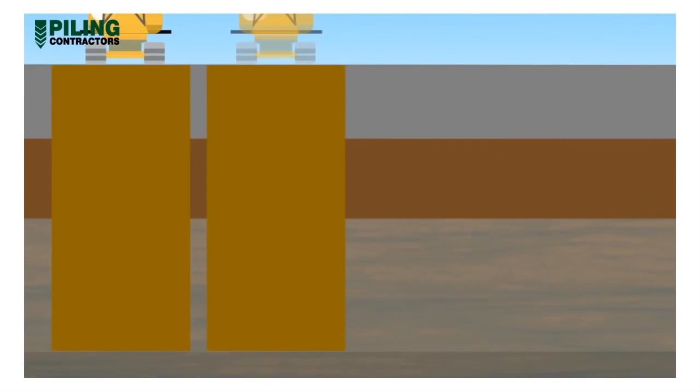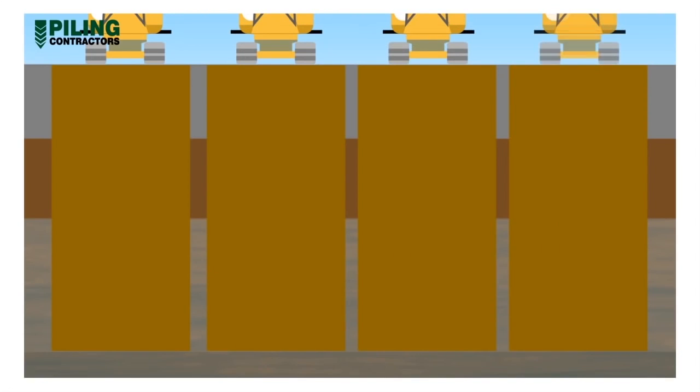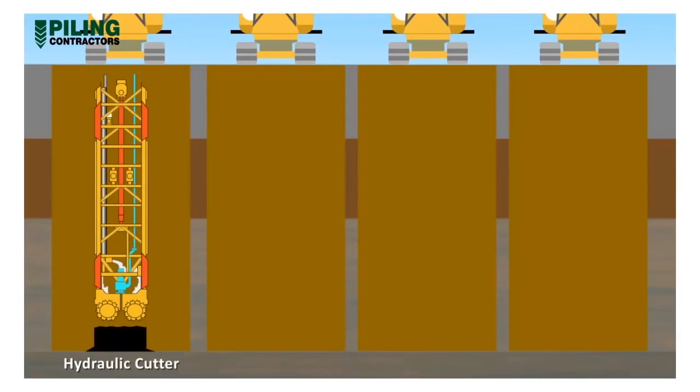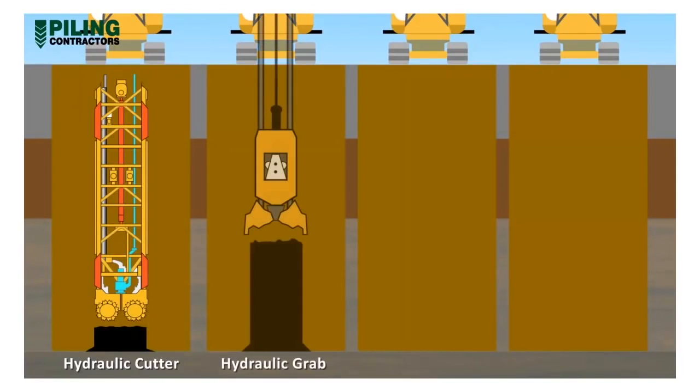As this panel closes up the length of wall, the stop end is removed from one panel during excavation of the adjacent panel. Diaphragm wall panels can be excavated using several types of equipment, including the hydraulic cutter. These are powerful machines capable of excavating into hard rocks but require large bentonite plants and a large crane to hold the cutter. Steering mechanisms are built into the cutter body to provide a high degree of vertical control.